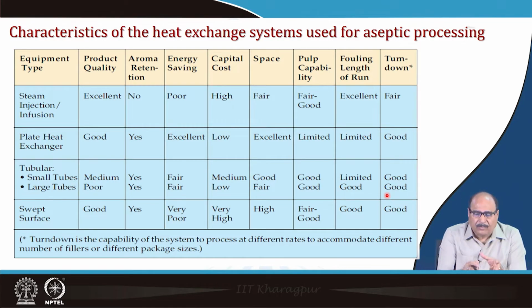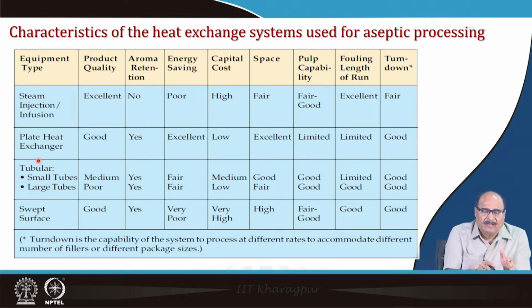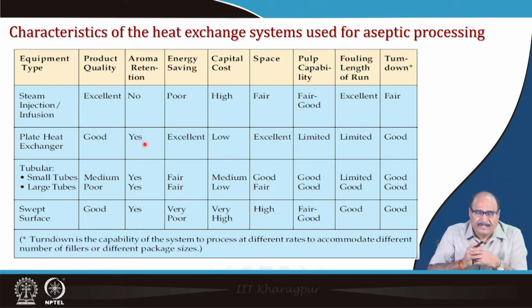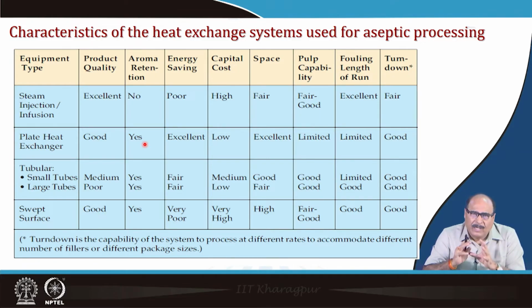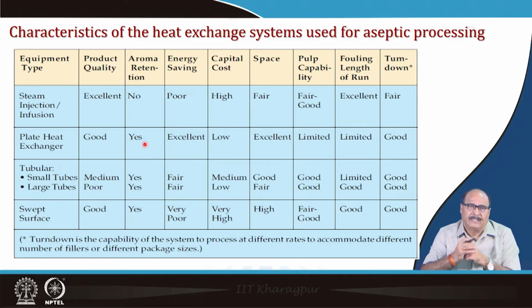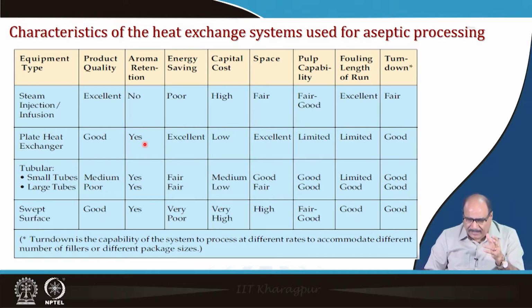From all other points, overall it is seen that the plate heat exchangers give fairly good product quality. Aroma retention is also good here. Energy saving is excellent. Cost required is also less. Space requirement is also excellent, reasonably good. And the turn down period is good. So, depending upon the product and its characteristics, one has to choose a suitable heat exchanger.